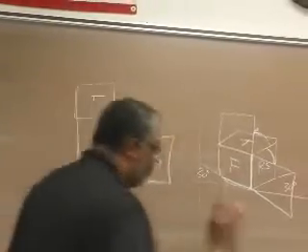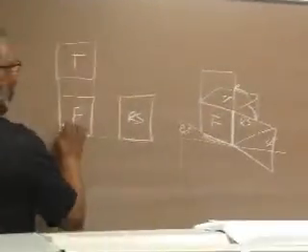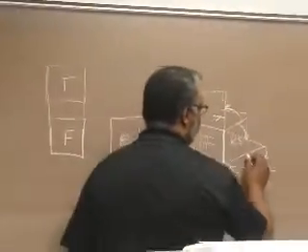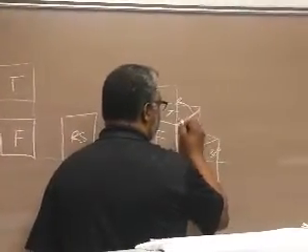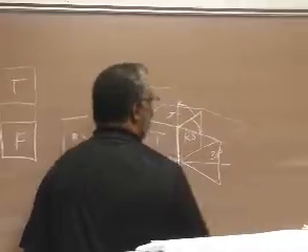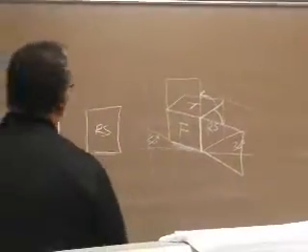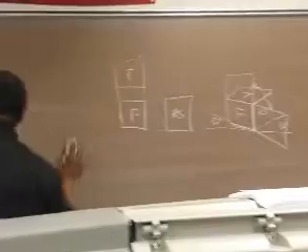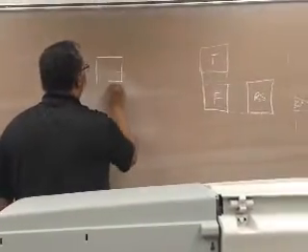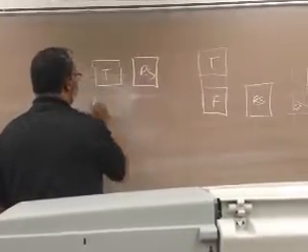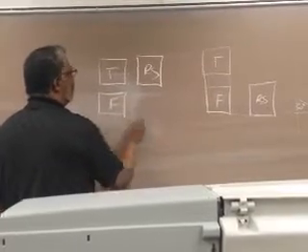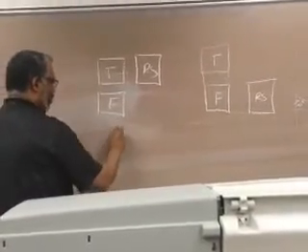That arrangement, you only have one option to that arrangement, just to let you know. Instead of hinging my right side to my front, if I hinge the right side to the top, it folds up right there. Then we have top, right side sitting right here, and then front sitting right there. This is your alternate arrangement.